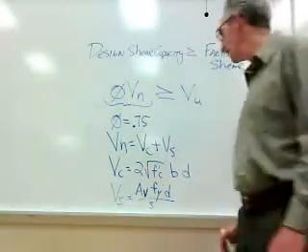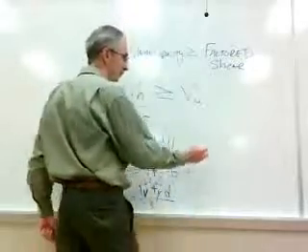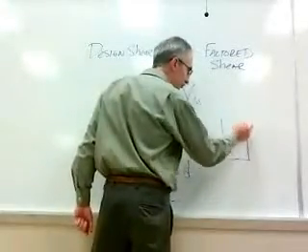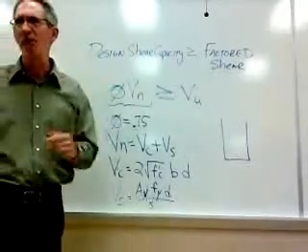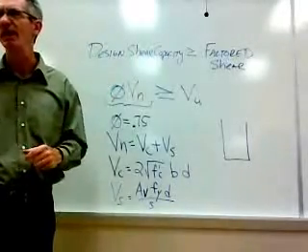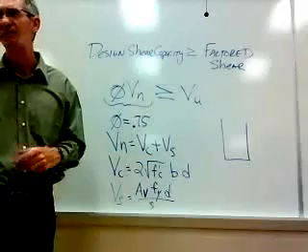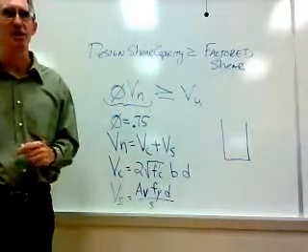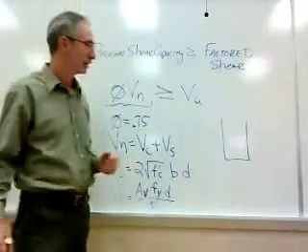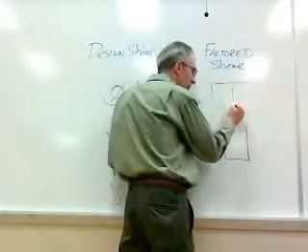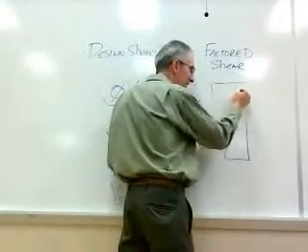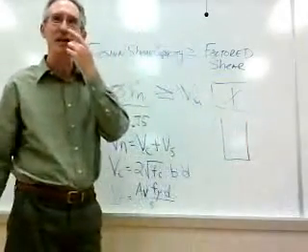Well, here's the deal with A_v. Remember how our stirrups typically are U-shaped bars? And they're probably going to be a small number 3 or number 4 bar. Maybe a number 5 bar sometimes. Probably 3s and 4s. And if you're looking at a beam, you see a leg that might be intercepting a crack, right?